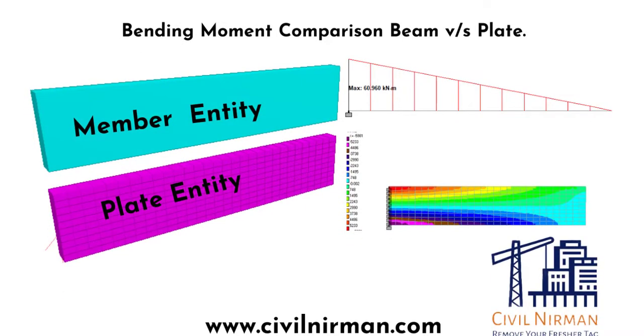In today's session, we are going to discuss a comparison of a beam element and a plate element. I have many queries from the students. If I model a particular beam element with the same dimension as a plate entity, will I get the same results? So the answer is yes. But you have to take care of a few important points while modeling the same element as a plate entity, right? Because it is a finite element model, and in that particular case you have to discretize your members and convert them into finer elements to get better results.